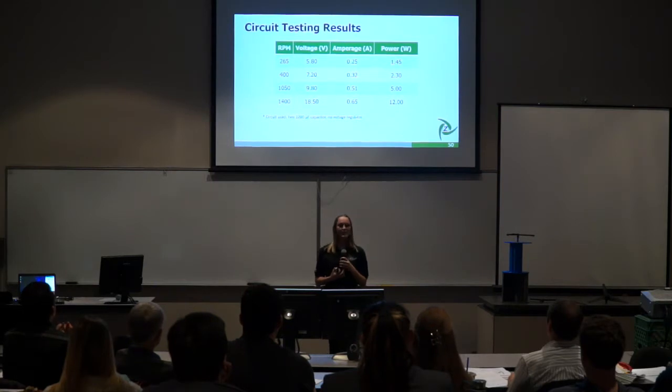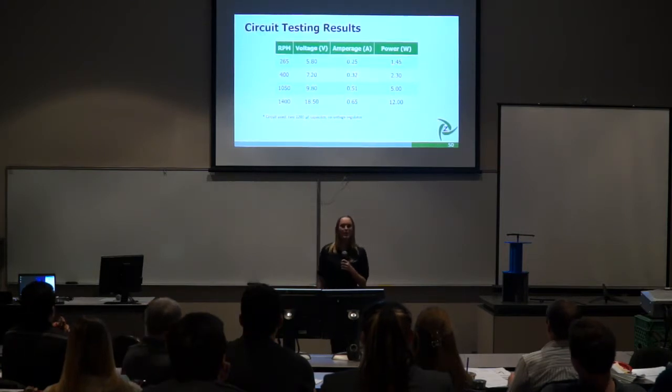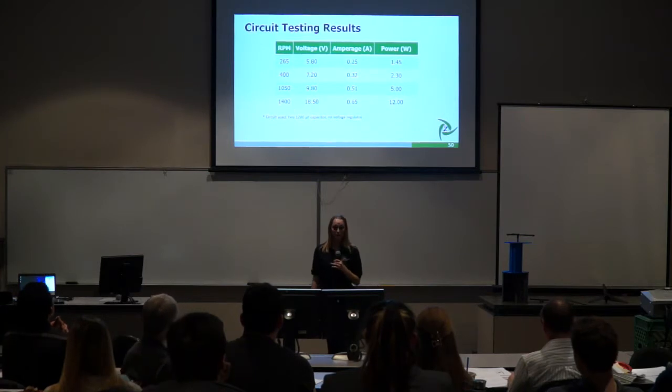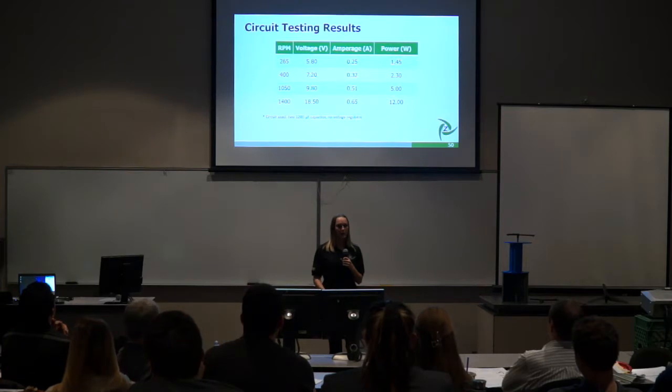At around 265 rotations per minute, the power output was approximately 1.45 watts. And going up to 1400 rotations per minute, the power output was approximately 12 watts. As I mentioned previously, the estimated rotational speed of our blades is around 1,000 rotations per minute.